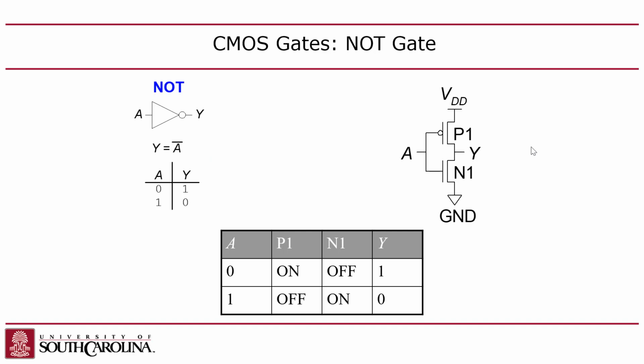Okay, so why is that relevant? Well, let's look at an example of an inverter, just a simple example first. An inverter has a single PMOS pull-up and a single NMOS pull-down, right? So if the input, notice the input is fanned out to both, and then the output is connected to the middle node. If the input is 1, it turns this guy on and this guy off, and thus Y will be shorted to ground. That means it'll pull Y down to ground.